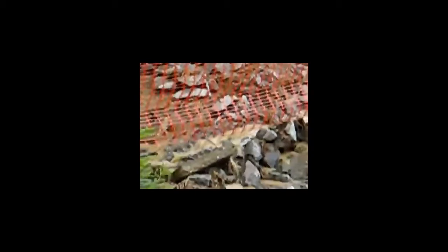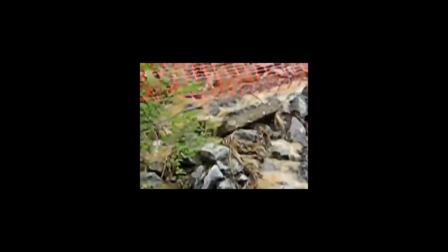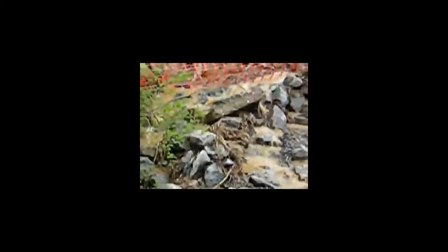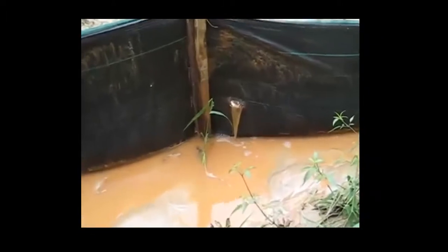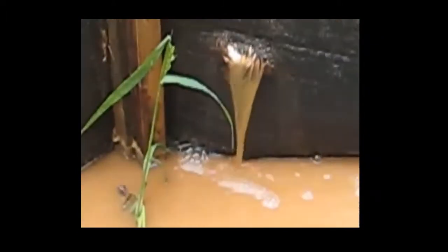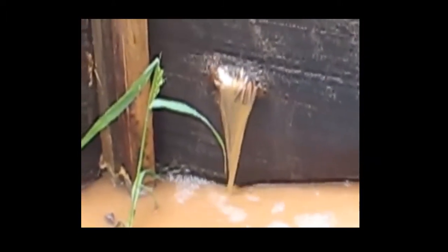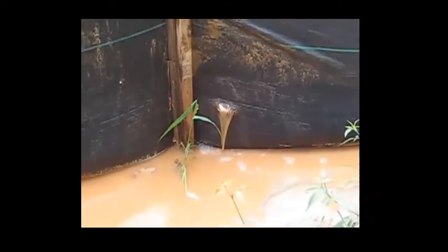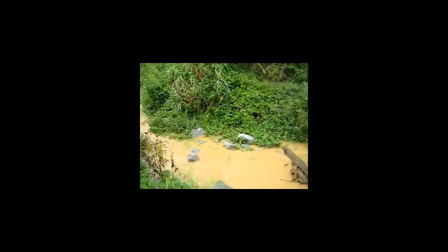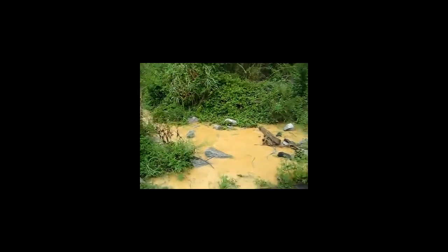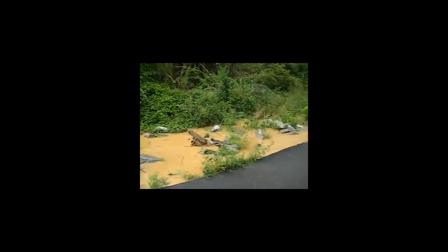As can be seen in this riprap structure, there is not enough protection to limit the amount of sediment traveling down. Additionally, this video shows a hole in silt fence where sediment is spilling out and traveling downstream from the site. Lastly, this video shows all of the sediment and runoff that is improperly being let through from the measures discussed previously.